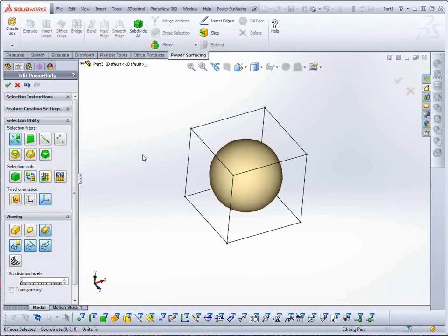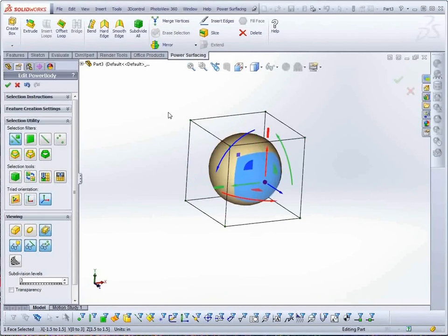Let's go ahead and move the mouse over the cage and model. As the cursor passes over the various elements or sub-objects, they are highlighted orange. In the Select Any mode, the default, you can select vertices, edges, or faces by picking the highlighted element. The selected elements will become blue. You can hold the Shift key down and continue picking, or Region Select to add to the selection. Dragging from left to right selects Windowed, while dragging from right to left selects Crossing.